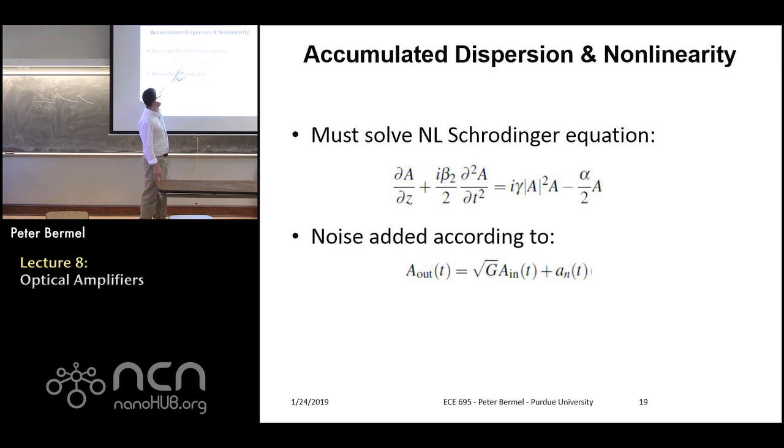And then if you plug it into here, you can track the effects of the dispersion, self-phase modulation and loss on both the signal itself as well as the noise, and see if the noise is actually being amplified to levels that will induce a huge amount of errors, right? Now, the catch with this equation is that because it's nonlinear, there's not really a good analytical solution.